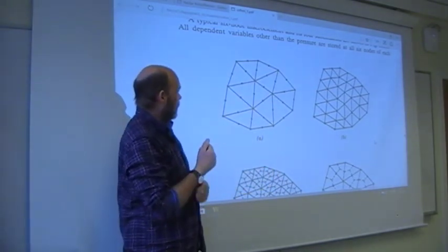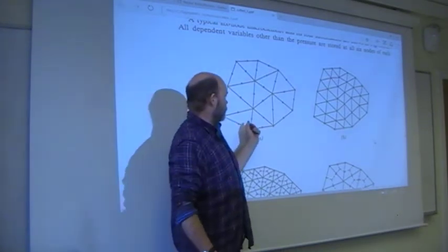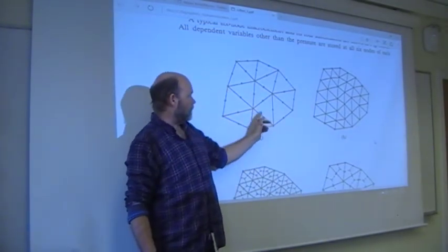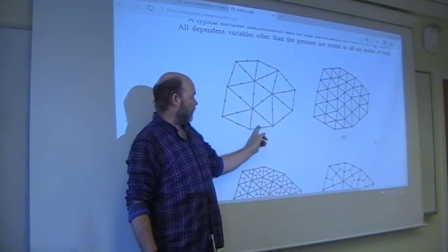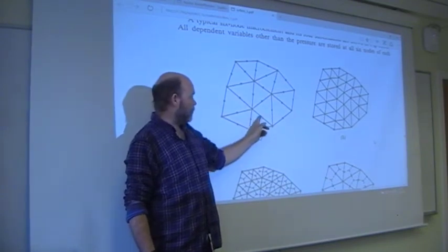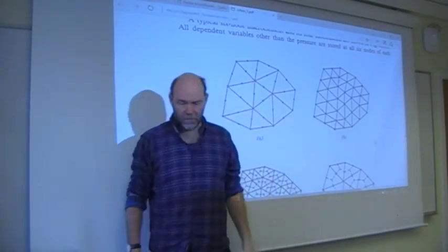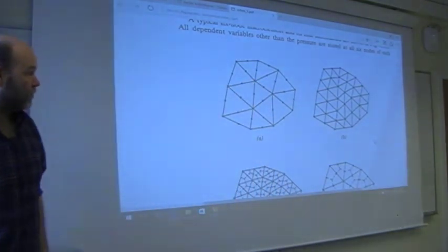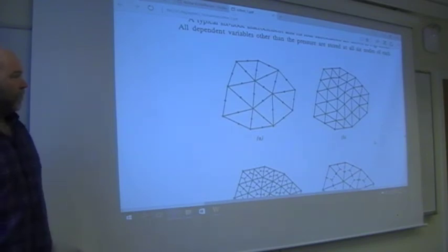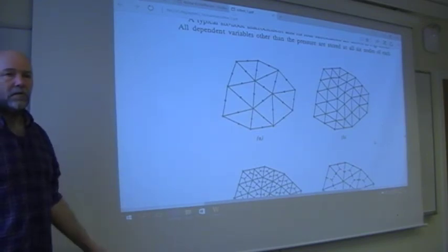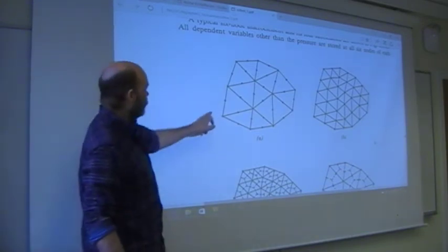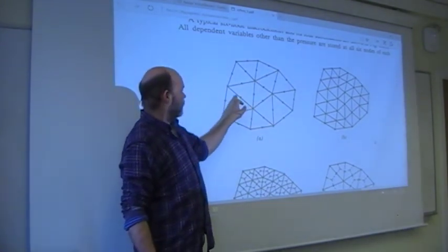Doesn't look too nice. So we create a submesh. When you have a triangle, it's fairly easy to create 4 triangles out of it. Just use the midpoints to obtain this mesh system. And then you use the fine mesh system there for velocities only. So the additional points here will be additional velocities.